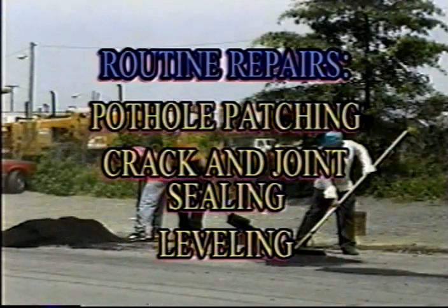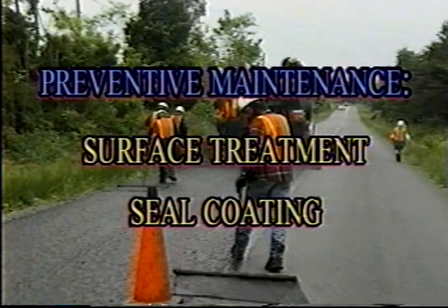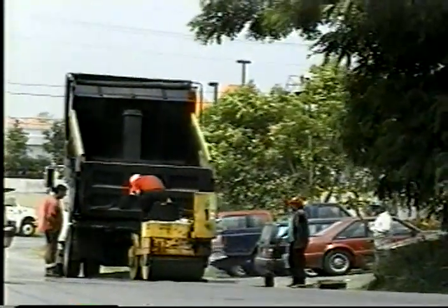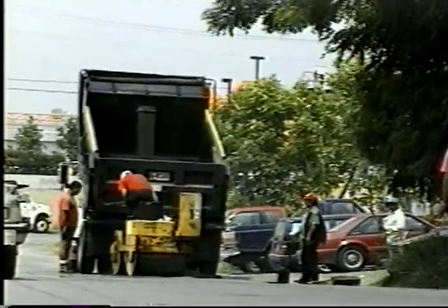Maintenance of road surfaces to keep moisture from entering the base through cracks in the pavement is vitally important to the stability of the roadbed. Surface maintenance can be divided into two broad categories. Routine repairs, such as pothole patching, crack and joint sealing, and leveling, and preventive maintenance, such as surface treatment or seal coating. The timing of both types of maintenance is extremely important to extending pavement life. There's truth to the saying, if you don't know what caused the pothole you fixed today, you will fix it again tomorrow.